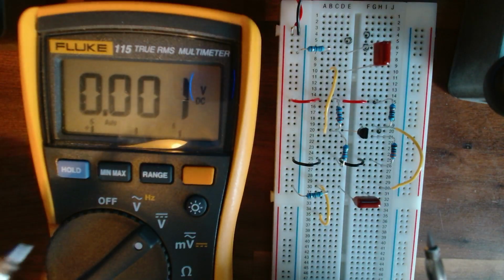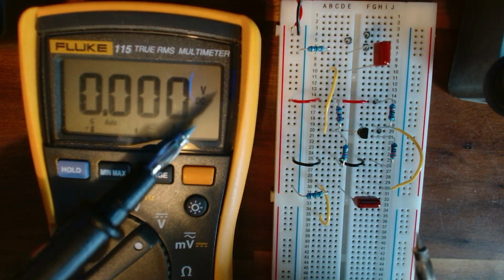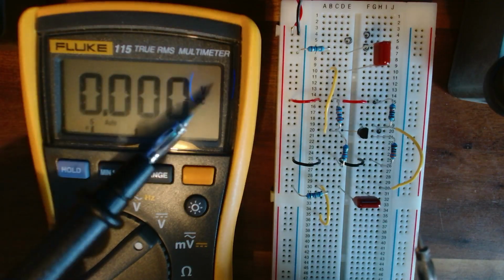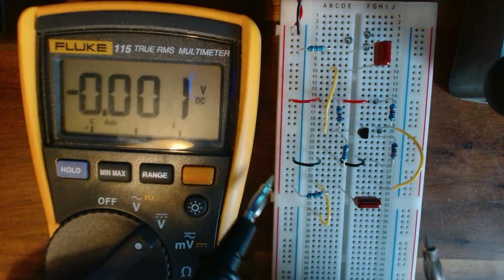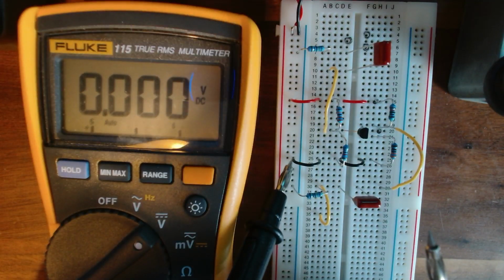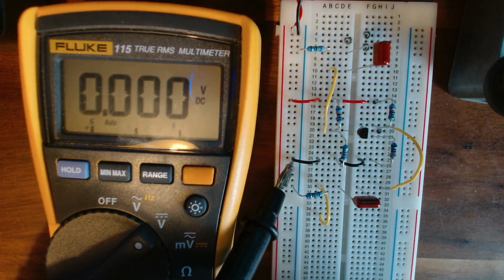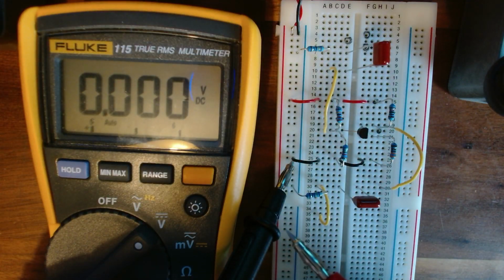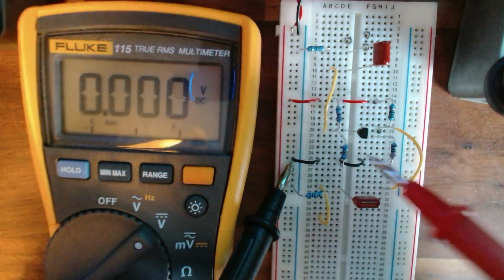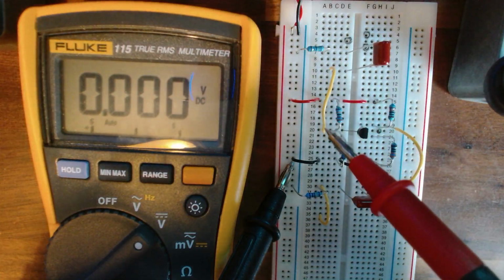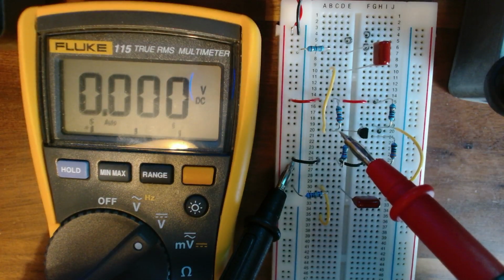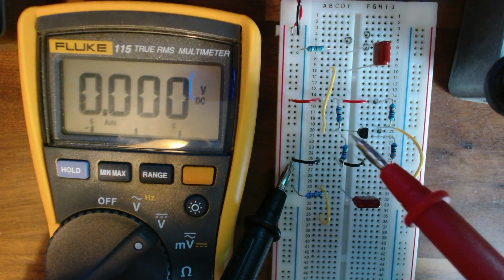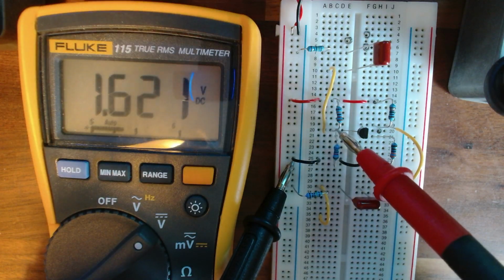So now that we know that we're accurate with our input power, we can start having another little poke around. Generally speaking, with DC you're working between 0 and your input number, in our case that 9 volts. So you can just park your black probe on the ground, on a black line, doesn't matter which one, and now you're just using the one to poke around and see what's going on.